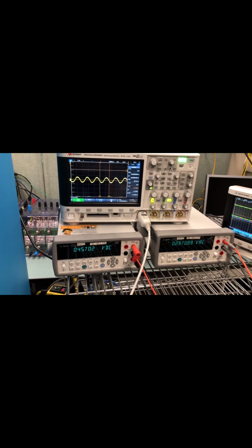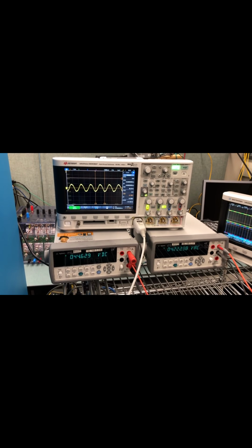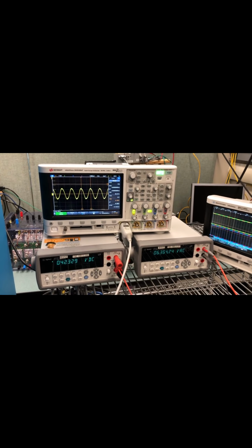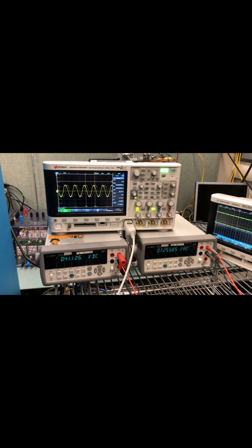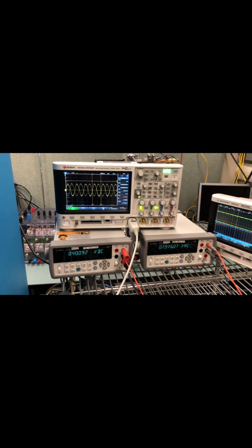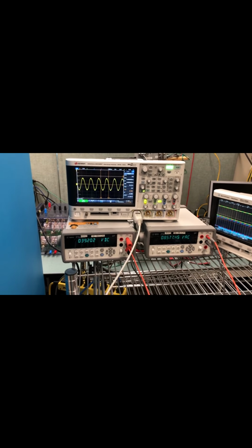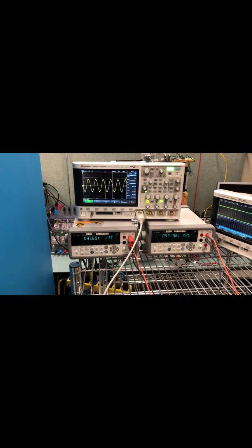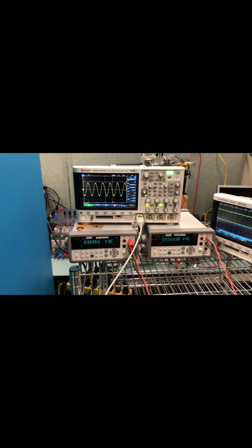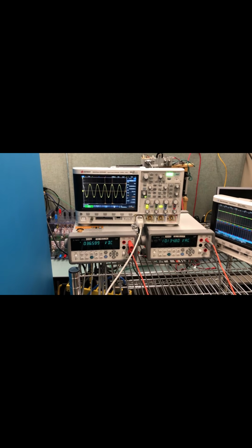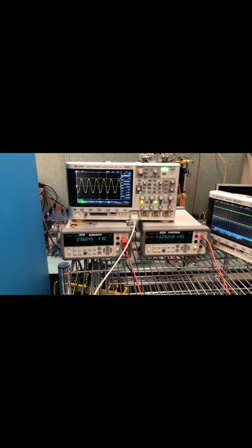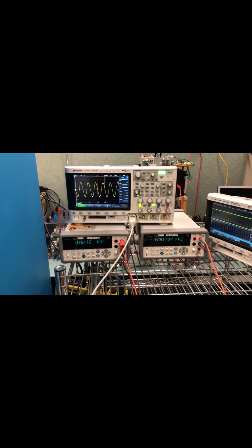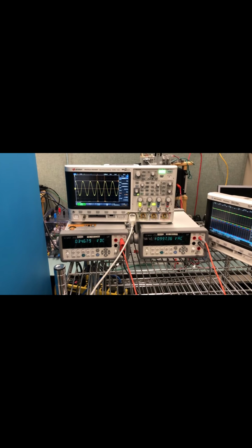This is the DC link voltage. Right now we are giving a 30 volt input, and we are trying to maintain an AC voltage of around 11 volts. So that's what we are trying to see, whether we can maintain our output voltage at 11 volts or not. As you can see over here, the sine wave at the output of our inverter, and we are trying to maintain around 11 volts.